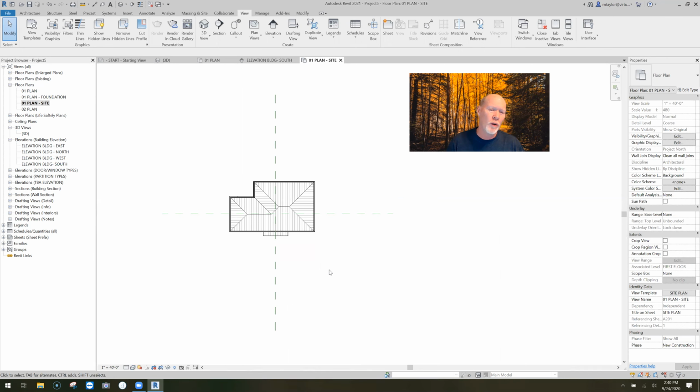I'm serious. I love Revit and the power of the true 3D. But if you've got a flat site, you don't need real topo. You can fake it in with a filled region on the elevations. You can just kind of fake it in. Anyway, but for those of you who need topo, let's talk right now. You and me, okay? This is us. Just focus, and here we go.